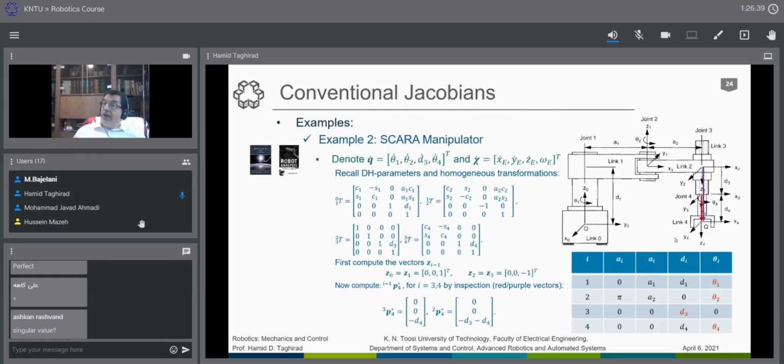Of course, we have found the Denavit-Hartenberg parameters in the previous section, and also the transformation we have found all before. Now we would like to go to the Jacobian. We should find the z_i's and p star. These 2 are important. Now we go one by one. Again, here, since the robot is simple, we can find the P stars much more easily by intuition. Somehow intuition, a bit more than the previous case. The z_i's are very simple.